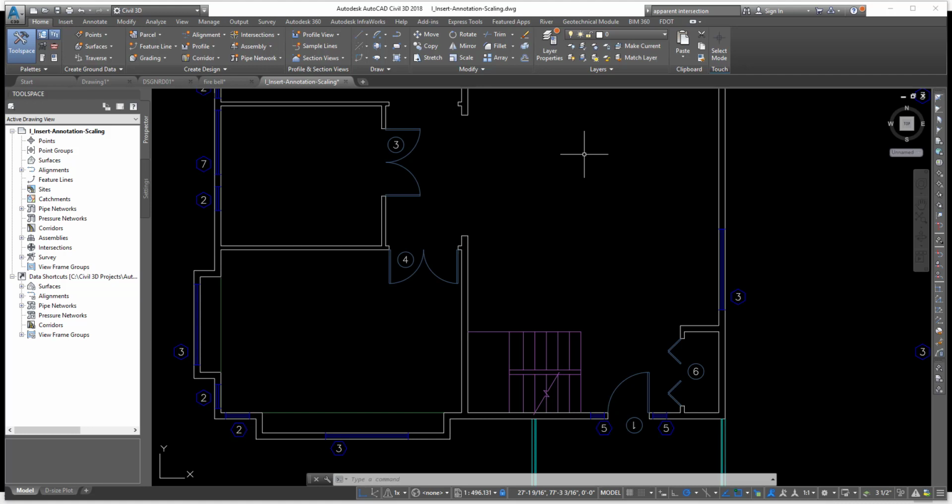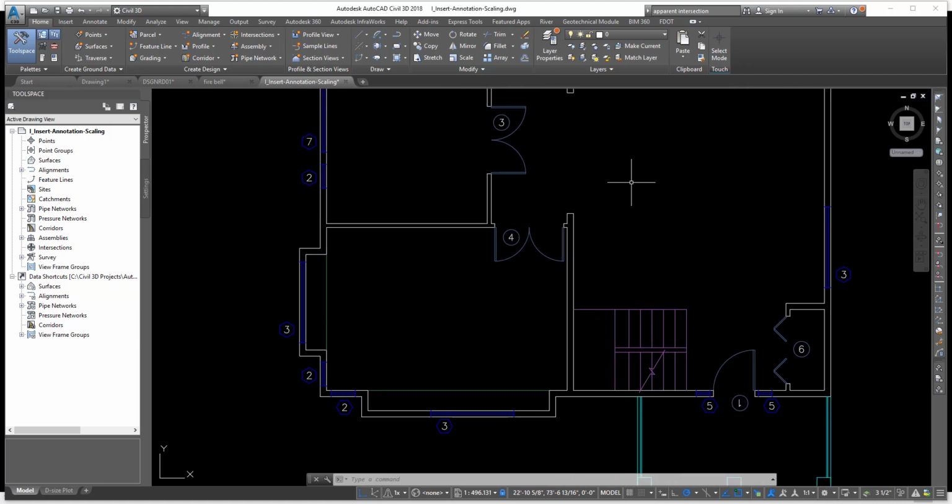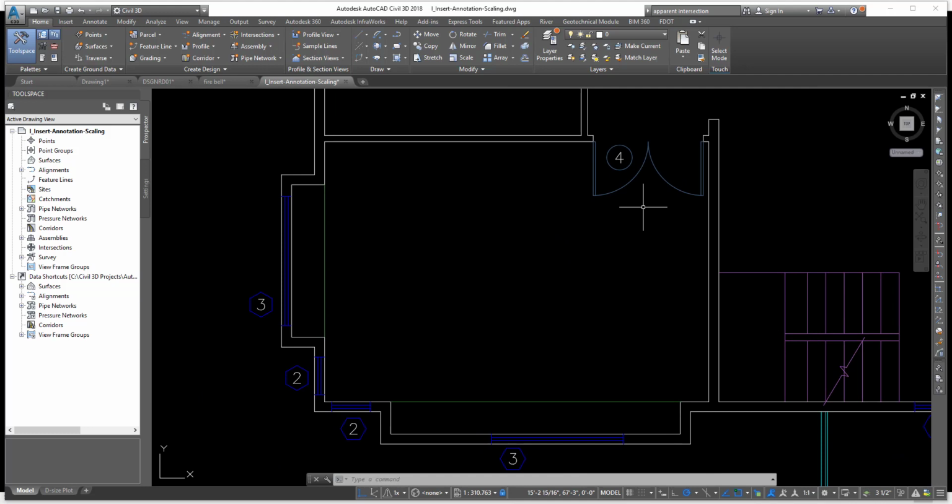If I create a block on a layer called Firebell and make it red, then every time I go to drag in that block, it's going to bring in that layer with it as well. So you've got two options there. I think the most common option is having the layer 0 set first and then creating your block, because this gives you some flexibility as to whenever you bring in a block, how it's going to react to layers.